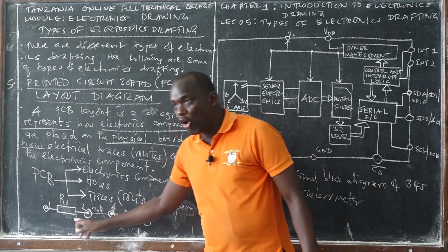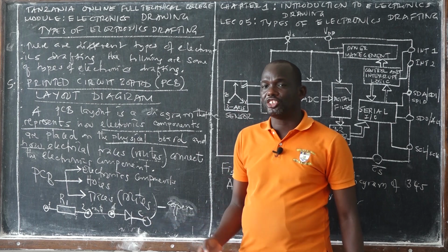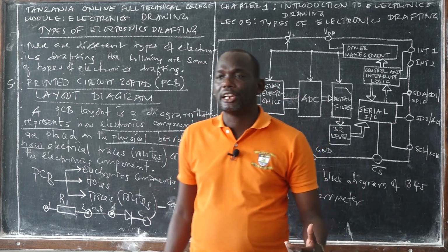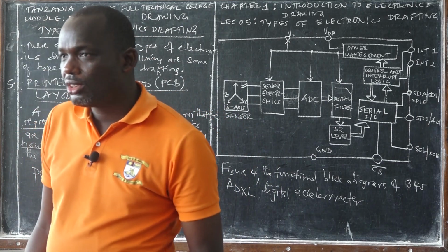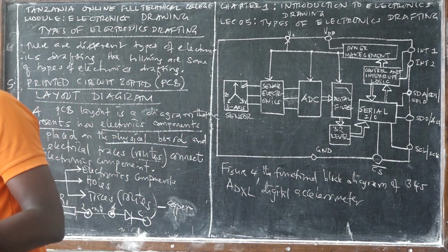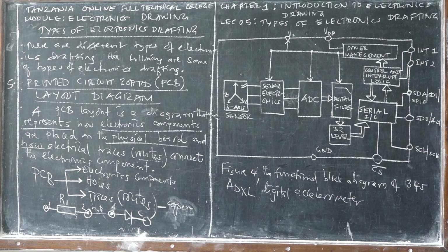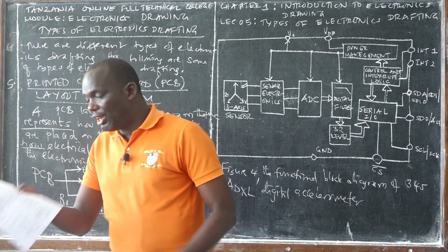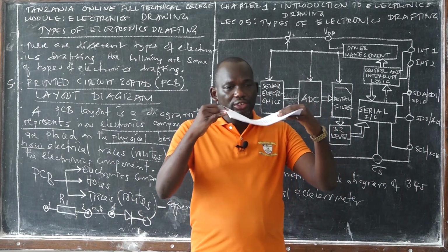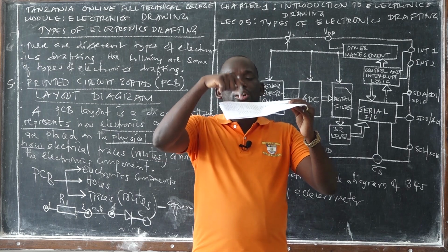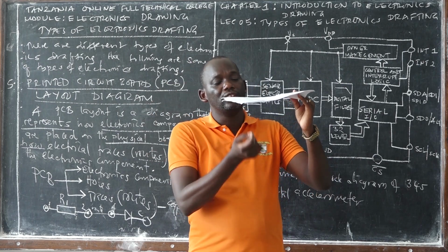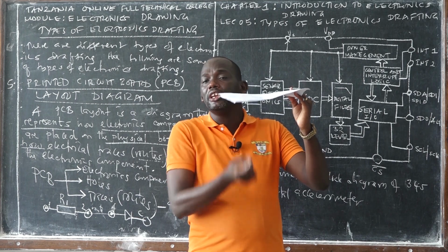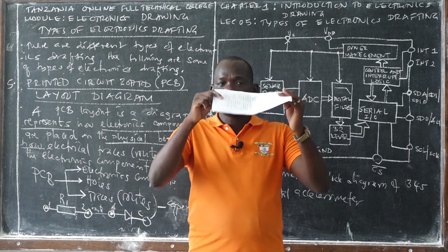We discussed the holes, because in electronics we have through-hole electronics components and surface mounting device electronics components. In other words, you have through-hole electronics components and you have SMD electronics components. The through-hole components need a hole so that you can mount that electronics component, and that pin or terminal should be on another side. Suppose that this is the PCB board.